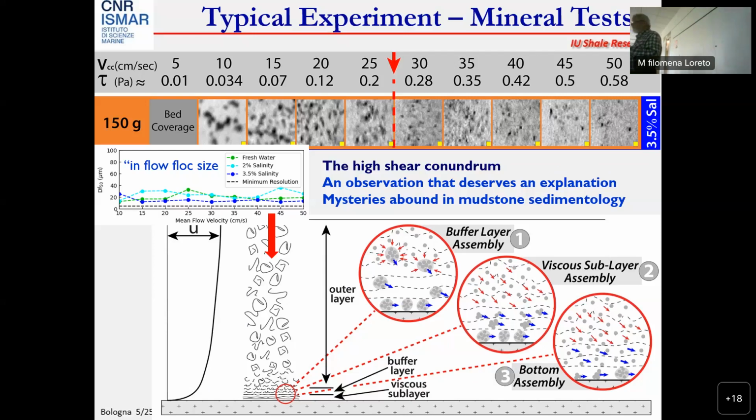And funny thing is, where we observe it, at the bottom of the flow. It shouldn't even happen. The floccules are basically loosely connected bits and pieces. Just a little bit of electrical force. And yet, at the bottom of any turbulent flow, the highest shear stress is right here.